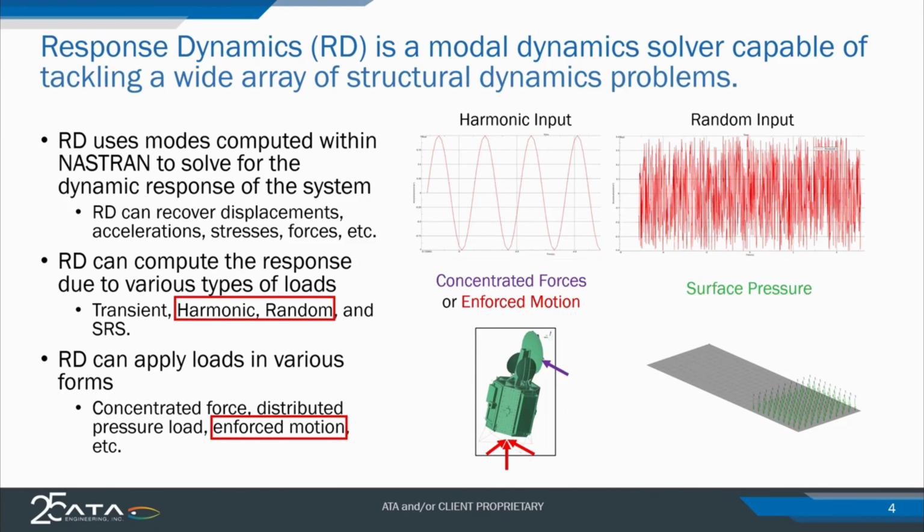So this means that in order to run response dynamics, you must first start with a modal analysis, solve for the modes of the system. Response dynamics can then use that modal solution to calculate response to a number of different dynamics situations. So response dynamics can compute the response to everything from transient analysis, harmonic loads, random analysis, as well as response